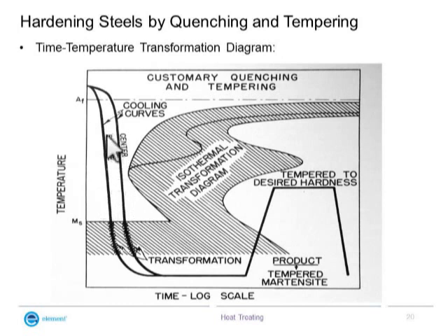You can see two curves. First, the surface which is in contact with the quenching medium gets cool fast, and the inside, the center of your component, gets cool later. This shows the first curve, the surface cooling curve, and the second curve shows the center part cooling curve. Here the curve is drawn between time and temperature. So this is the time duration between the surface and the center to cool, and this is the S curve.